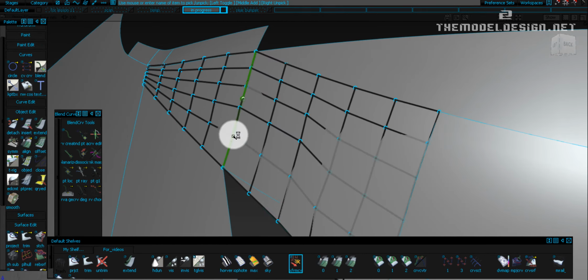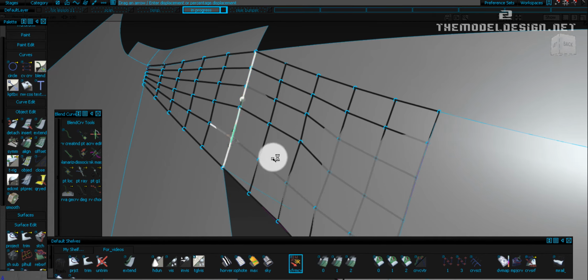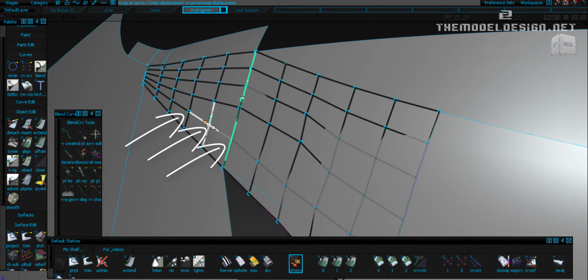Here, we are sliding CVs to get a better layout. There is no rule as to how many CVs should be slid. It's a good practice though to slide 2 or even 3 CVs that sit on the same hull.